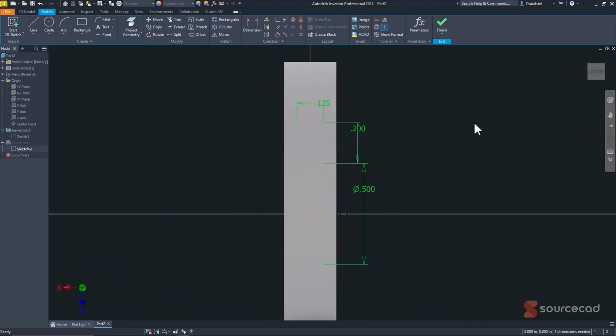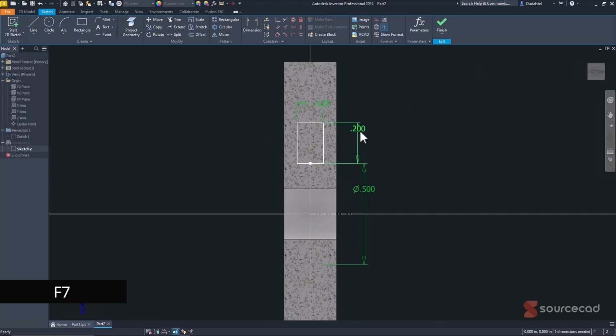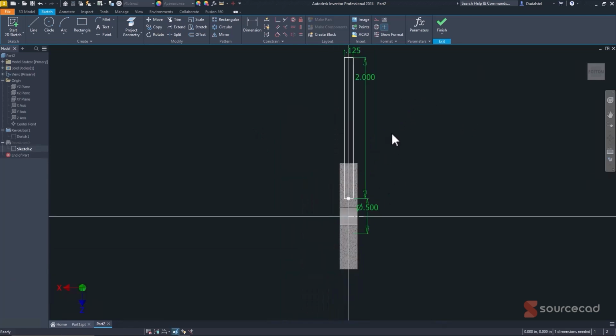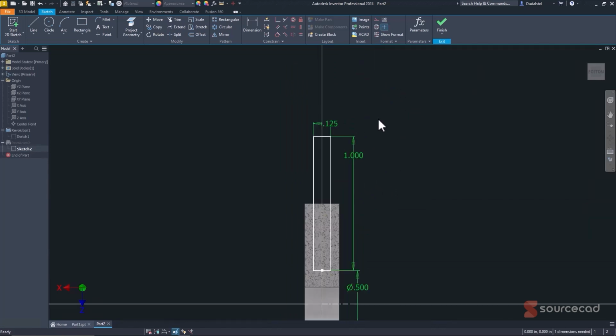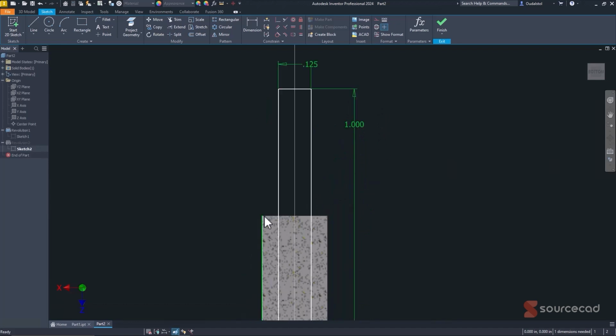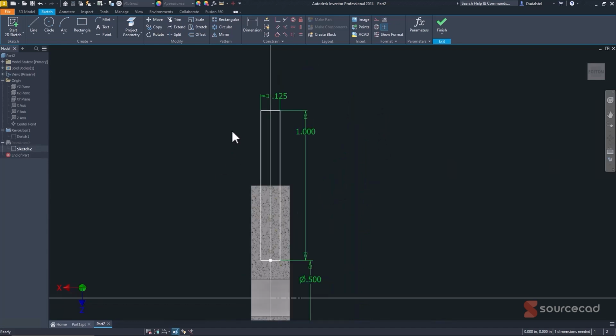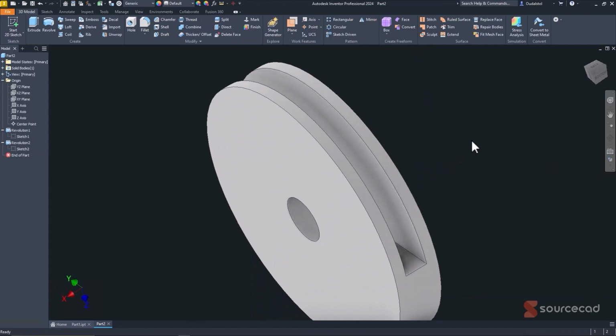And again, remember F7? Okay, this needs to be, let's just again exaggerate, using 2 inches. This is excessive, I'm aware. We can do 1 inch. Or you could potentially project out this outer edge if you wanted to. That works just as well. And so dimension yourself above it. But you have the same capabilities as extrude. You can go back and edit your sketches as you go along.